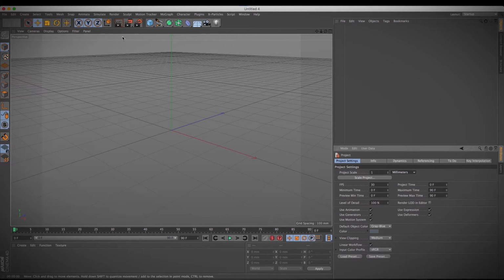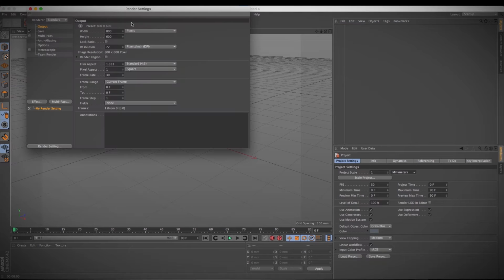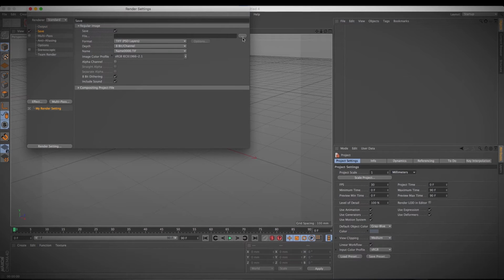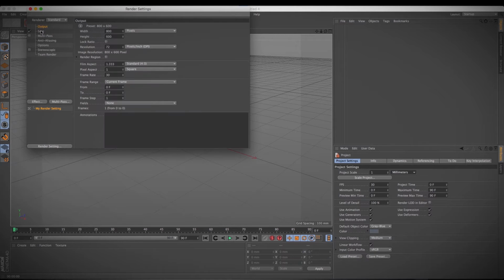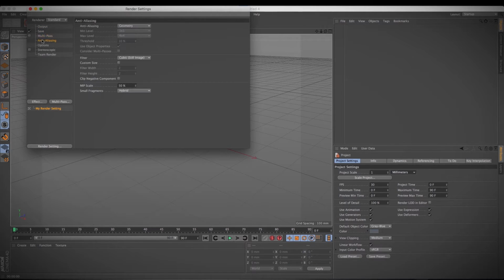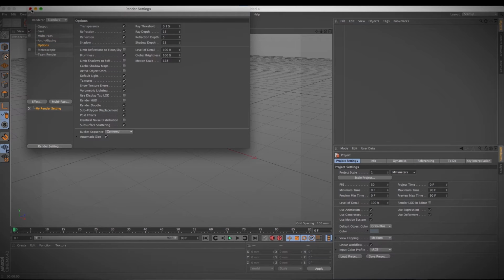The next set of icons are mainly for rendering. The only parameter we should set up is a location to render out images should we need to use them. By clicking this third button, we can set up our save location. In the Save menu, click on the three-dot Location menu and create a render folder in the same folder as your main file you save for your images. In model building, these other settings are useful for animation and such, but we really won't need to change anything here for this episode.